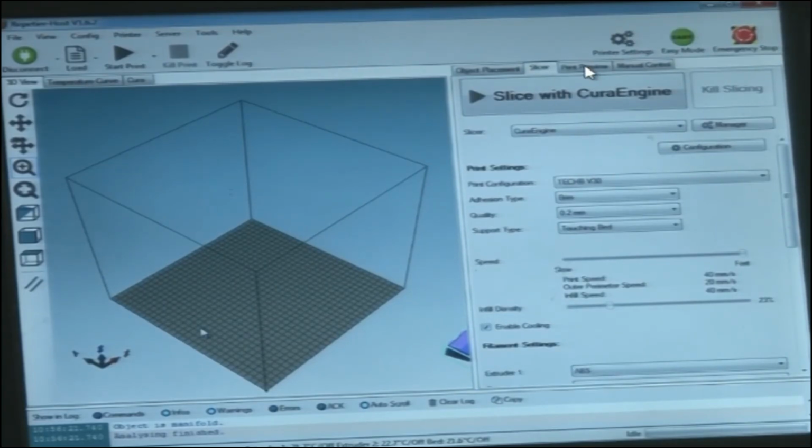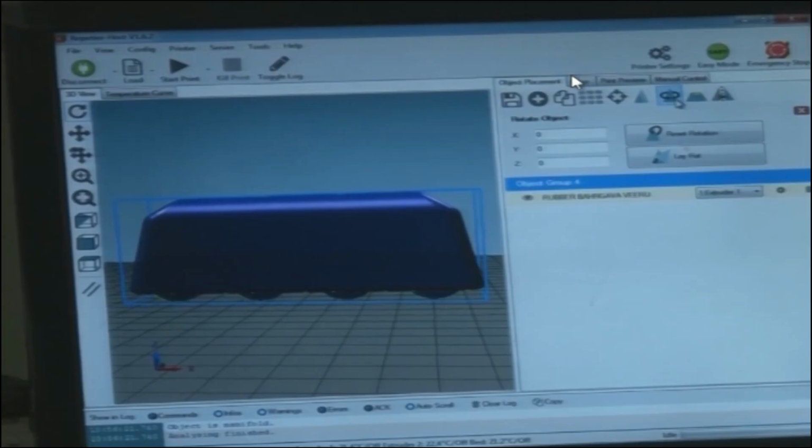So we are still working in this slicer tab. As we discussed before, the slicer is the most important tab in this software, I feel, when we need to decide. Most of the parameters are decided here only. Print preview is just a preview, and manual control is for when we need to control the machine manually, when we do not trust the G code, or rather this is not a question of trust, it is about when we need to make some modifications according to our requirements, so we can machine in lesser time, or induce some new features. Whenever we need to do something manually, manual machining control can be used.